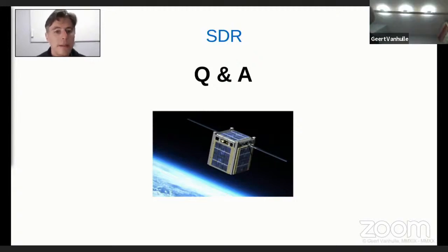Yes, so that's exactly why we need these high-speed CPUs. You've understood directly one of the problems that we have in software-defined radio: the delay in the whole flow graph. Of course, every processing step will add some delay, but we have this in analog circuits as well. This is often underestimated, but analog circuits also add delay. Of course, it's of another range, but it can be a problem there as well. The difficulty with analog propagation delays is that they're very nonlinear. So if you have a certain bandwidth, the propagation delay at a certain frequency risks being different at another frequency, which causes a huge set of problems in the analog field. In the digital field, the delay will be higher, but it's linear. So you get rid of a lot of problems on that side.